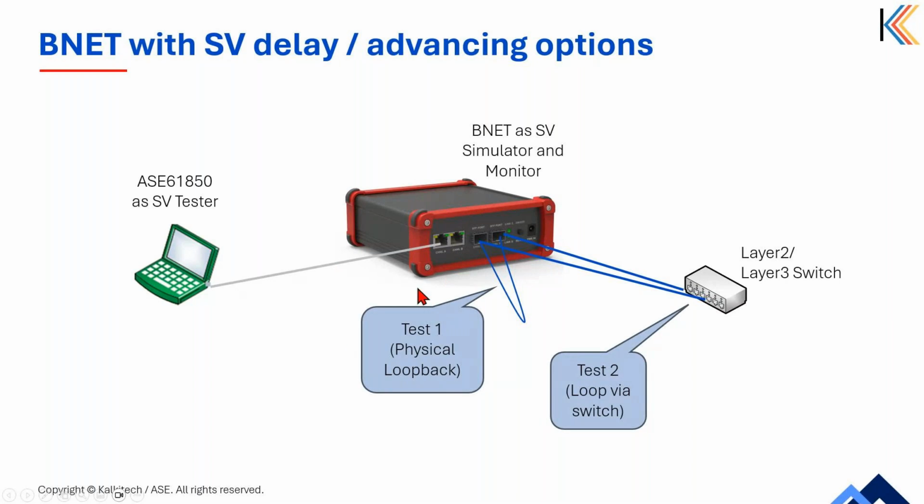Based on the PTP synchronization, all the publishers will be sending signals, and the devices or relays will be expecting these sampled values to reach their port within that interval. So how will you find out the behavior of the device when there is a network delay, or when there is some kind of anomalies in the network where some devices could not get the PTP signal properly, and if they are out of sync.